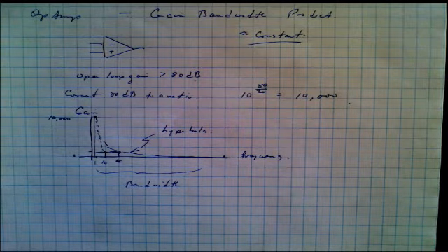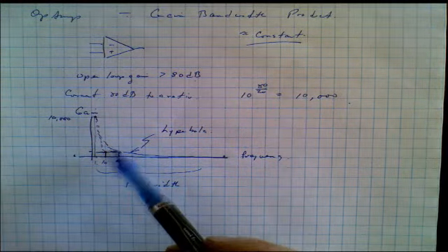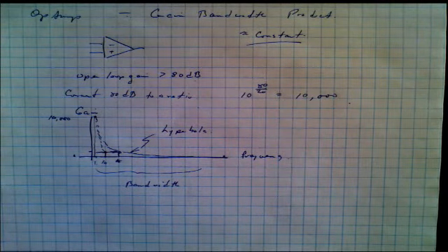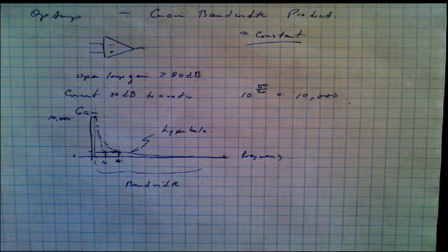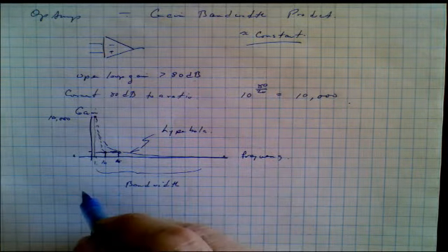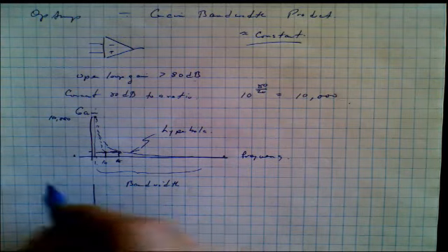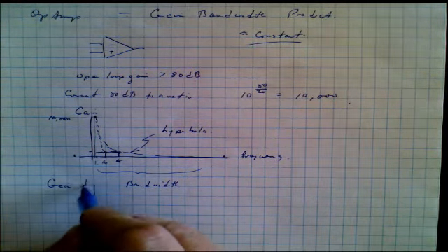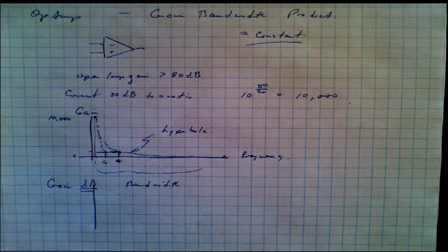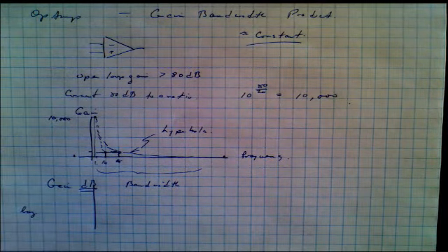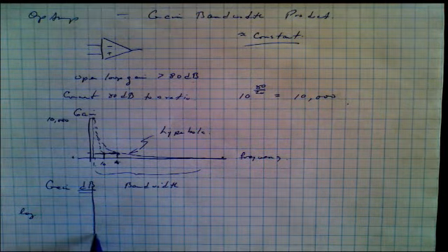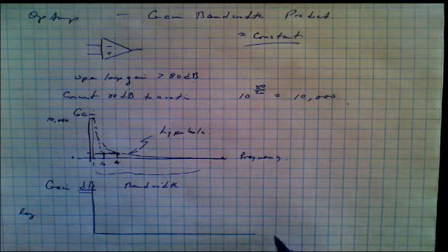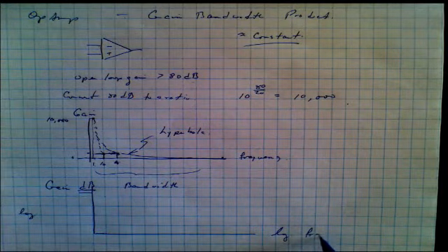The reason why this is causing problems is simply because we're looking at a curve. So how can we go about redefining this axis, this solution space, this gain frequency domain into something that will give us straight lines? Well, the one way to do that is to make the gain in dBs. Decibels are really a log scale. They're a logarithmic scale. And if we take a look at frequency, we can do exactly the same thing. We can have the log of frequency.